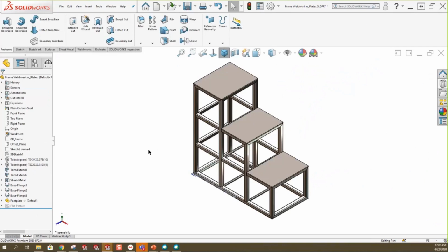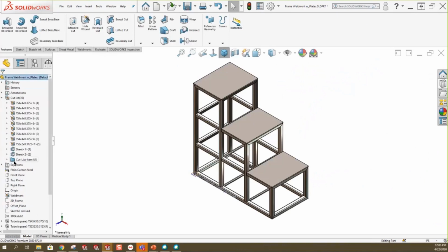Would the inserted part show in the drawing, BOM or cut list? Absolutely. If I take a look now, there is that body right there with the foot plate. The cool thing about this is if you have a file that you use over and over again, maybe this thing's got wheels. Maybe I've got a part file that's just caster wheels. Maybe I download it from McMaster-Carr or whatever it might be. I can over and over and over insert that information to here.